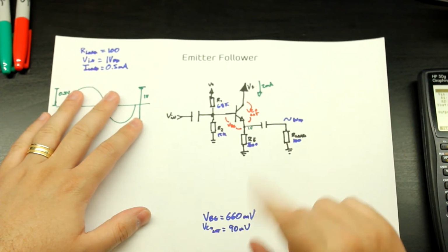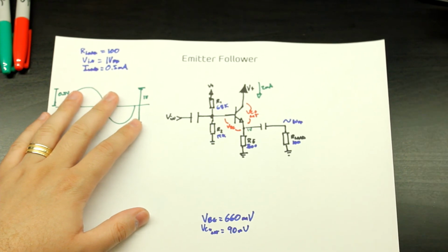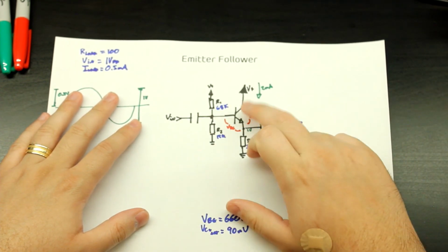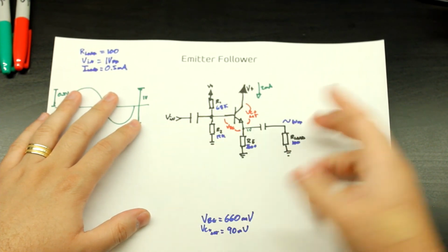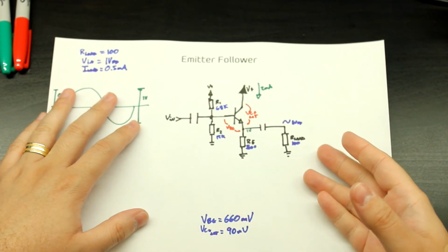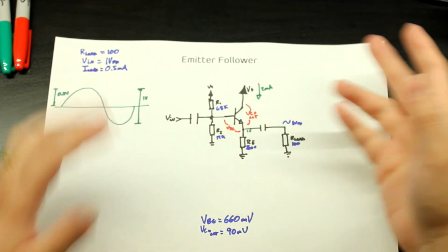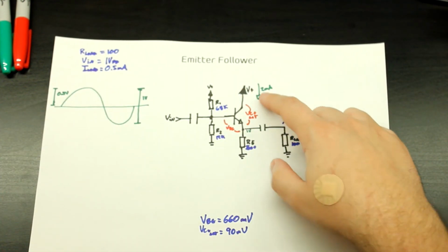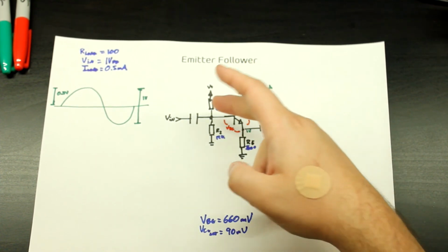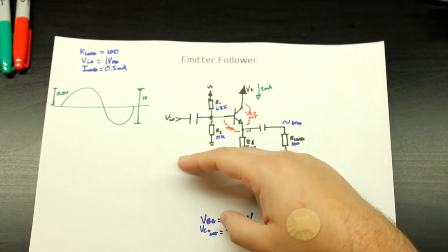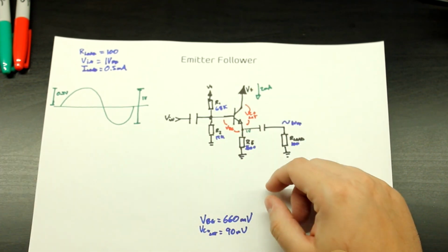So now let's take a look at a different configuration for this transistor, which is very simple, because with this transistor, for these low currents, it's not a problem. With one transistor, you get enough current, enough gain, enough HFE here, so that your input impedance here is relatively high.